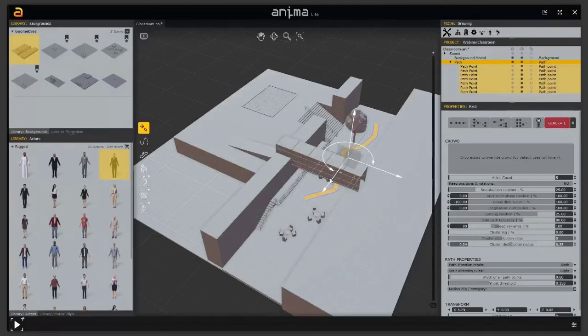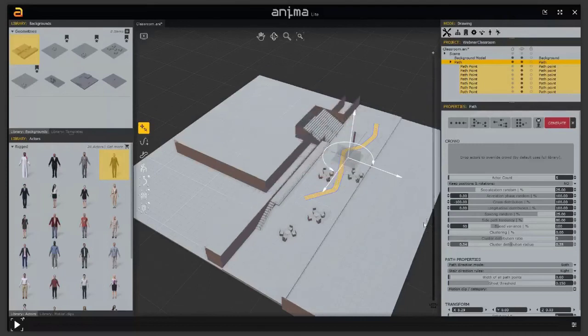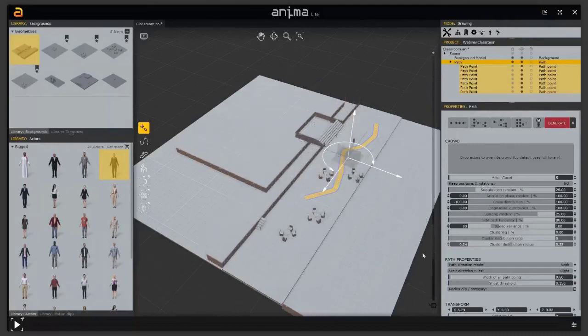Now, going back and forth with this bar, okay, it's okay, but something better is to create some bookmarks, okay? So for example, I have this part here. I want to just work on the bottom floor. So what I can do is just set the section and right click and add a point at current height, as you can see here. And this little dot appears.